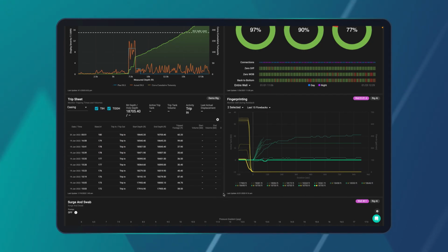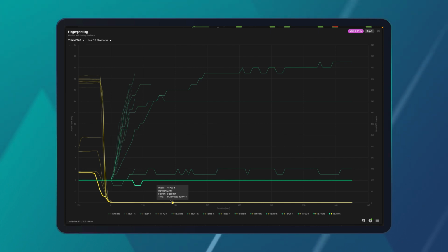The other tools here I want to focus on are related to well control monitoring, flowback fingerprinting, very common, especially offshore. So basically, what is the behavior of the pits or the flowback to the active pits here in green every time you kick the pumps off. I also have here flow in. So when you kick the pumps off, you can see that for reference. We can also pull in flow out. If you want to do a flow check on the trip tank, you can see that. So very nice here. I also like that you can do look backs very cleanly.